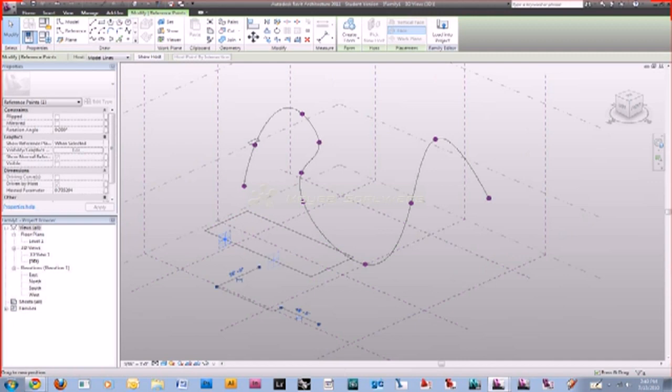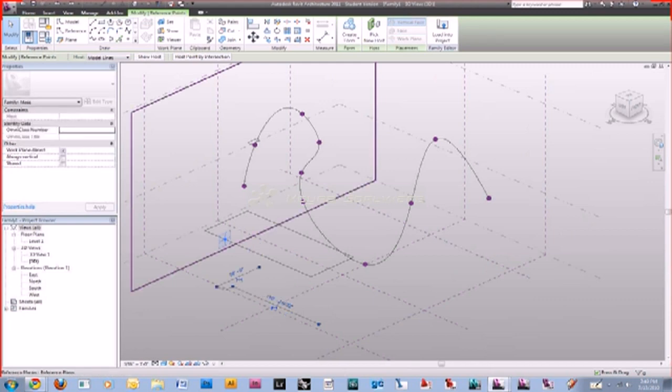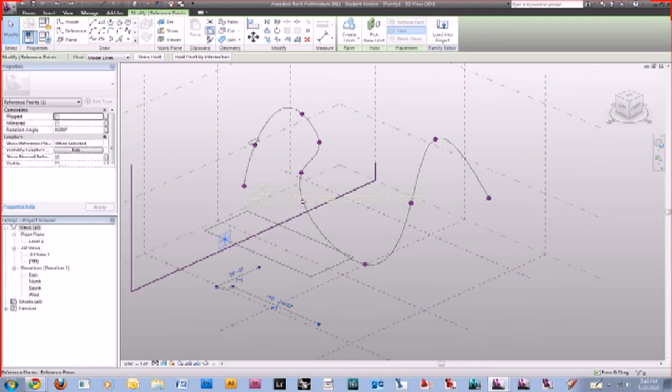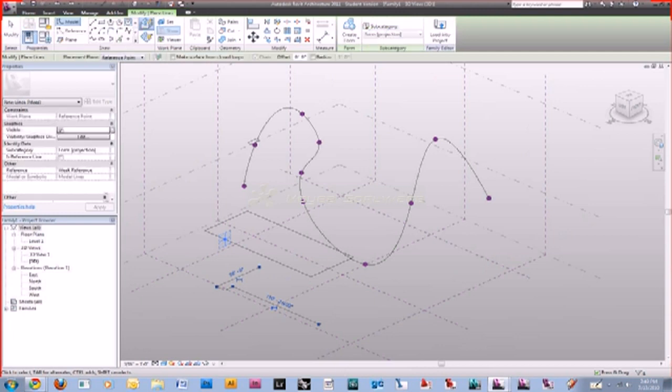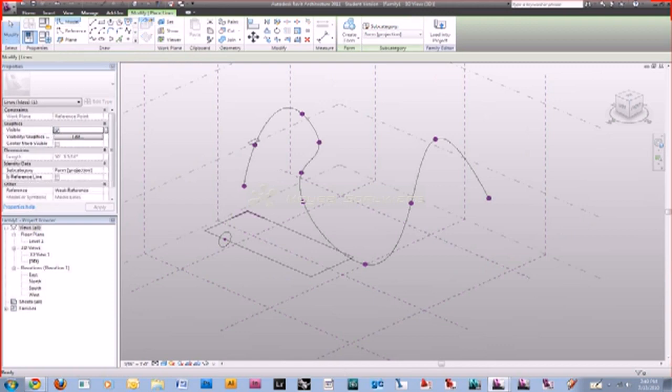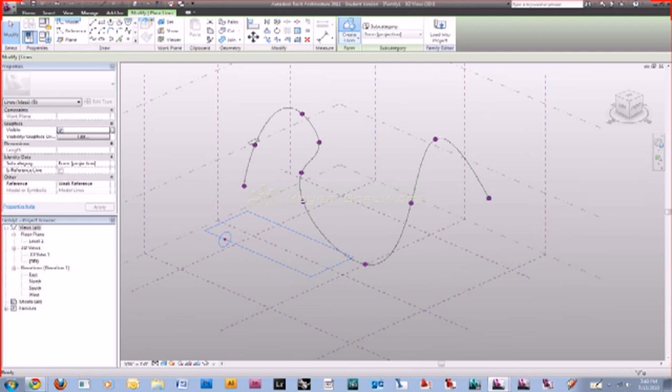And now that point should be hosted by that line. And this is another thing, you notice he didn't put the point in the corner. You don't want to put a point in a corner because then two reference planes pop up and it kind of gets confused every once in a while. Just like you don't want to select the end point of a sweep, just out of good practice. So anything can be swept around any object. It doesn't matter what it is. And it's kind of neat to watch how it bevels the edges and stuff. So it's mitering them at 45.